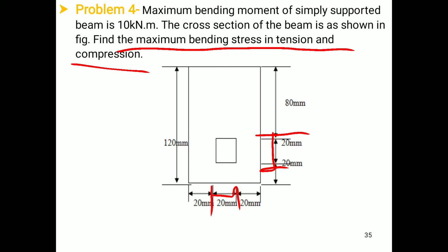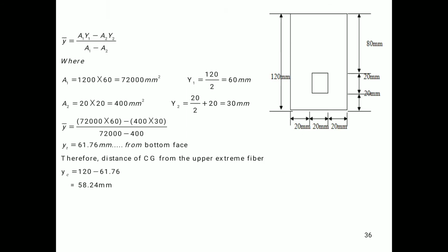Remember that again we are going to find out the value of stress induced into the beam by using the flexural formula. To find out the value of stress, again we will find out the value of I and the value of YC and YT. We are not going to find out the value of M because the value of M is already given in the numerical. It is 10 kN meter.